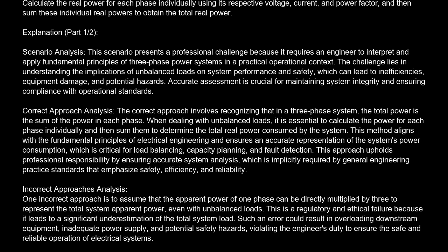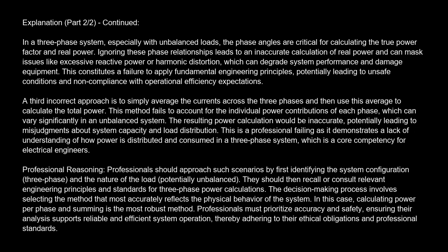Another incorrect approach is to focus solely on the voltage and current of the system, without considering the phase angles between them for each individual phase. In a three-phase system, especially with unbalanced loads, the phase angles are critical for calculating the true power factor and real power. Ignoring these phase relationships leads to an inaccurate calculation of real power and can mask issues like excessive reactive power or harmonic distortion, which can degrade system performance and damage equipment. This constitutes a failure to apply fundamental engineering principles, potentially leading to unsafe conditions and non-compliance with operational efficiency expectations.